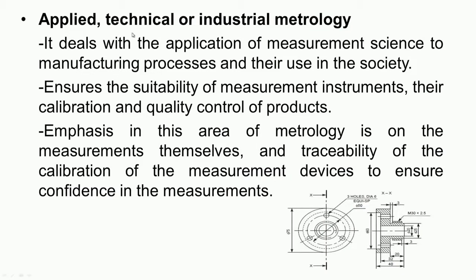Now we will move to applied, technical or industrial metrology. It deals with the application of measurement science to manufacturing processes and their use in the society. It ensures the suitability of the measurement instruments selected and their calibration and quality control of the products. So in this area, emphasis is given on the measurements themselves and traceability of the calibration of the measuring devices to ensure confidence in the measurements.